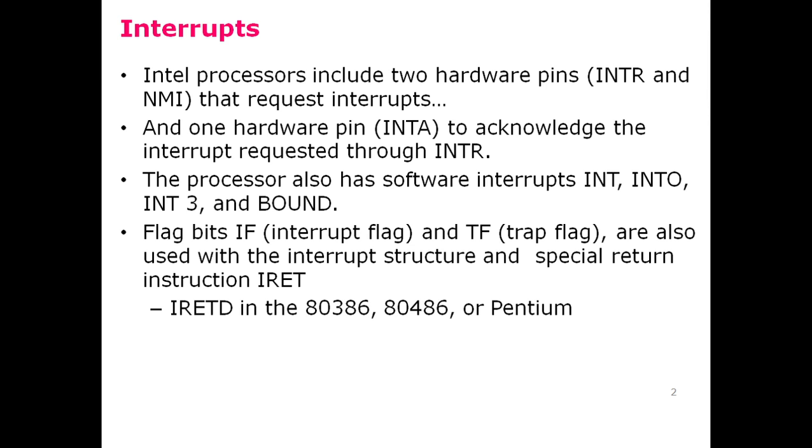Similarly, the microprocessor also has software interrupt instructions, INT, which stands for interrupt. This is an unconditional interrupt instruction. There is a conditional interrupt instruction, INTO, that means interrupt if overflow. So if the overflow flag is 1, then this interrupt will happen. And then there is a special interrupt called INT3. And then there is a BOUND interrupt. This is also a conditional interrupt.